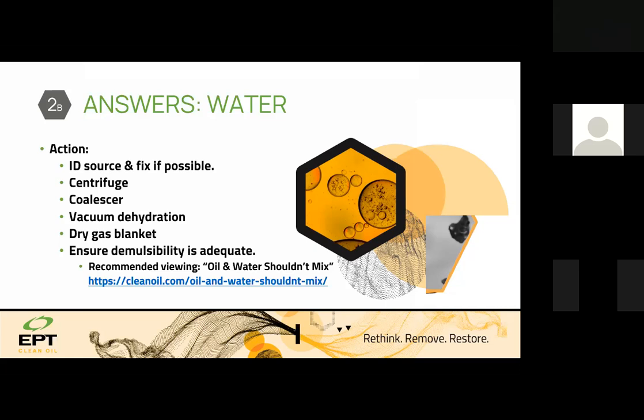We are doing two things here. We remove oxygen, so we slow down oxidation. And even if there is some moisture inside the lubricant, it can go back to the nitrogen on top. So it's a water removal technology, removing the source of water if it is from the moisture on top, and it can even slowly absorb water back into the gas.